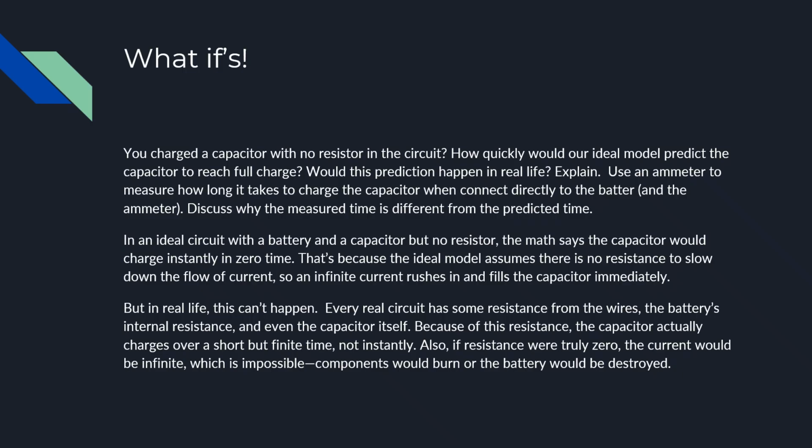But this won't happen in real life because every circuit has some resistance from the wires, the battery's internal resistance, and the capacitor itself. Because of this resistance, the capacitor actually charges over a short but finite time, not instantly. Also, if the resistance were truly zero, the current would be infinite, which is impossible. Components would burn, or the battery would be destroyed.